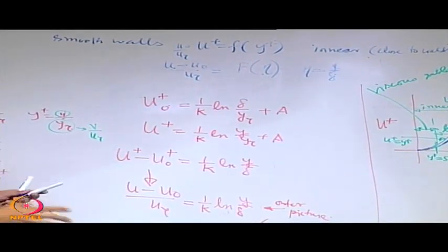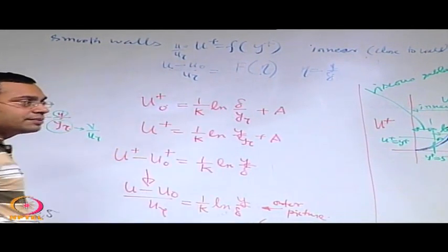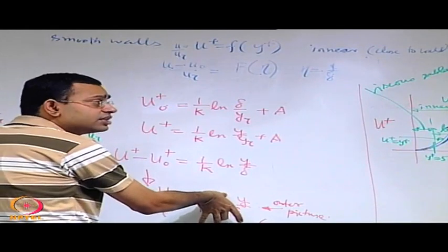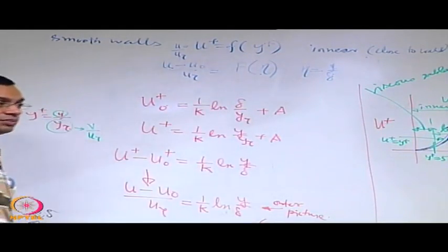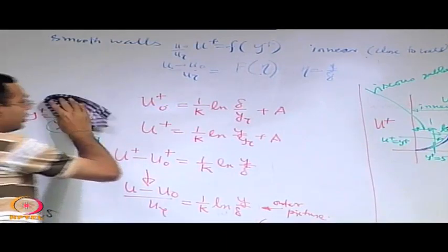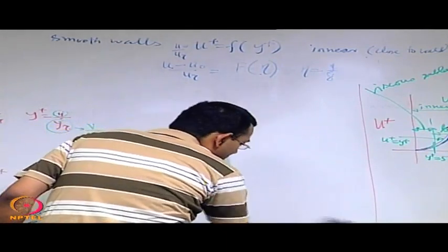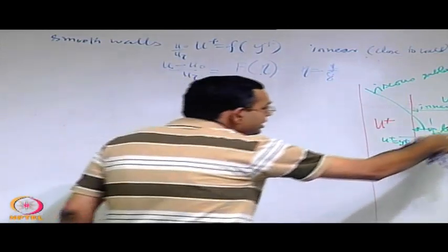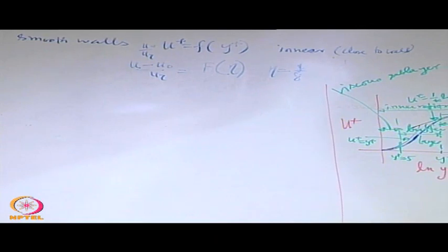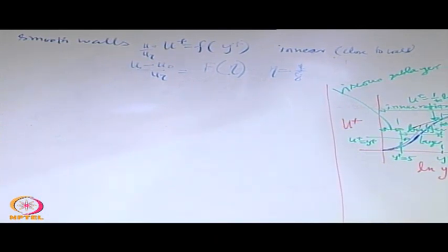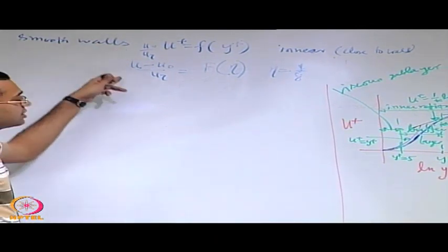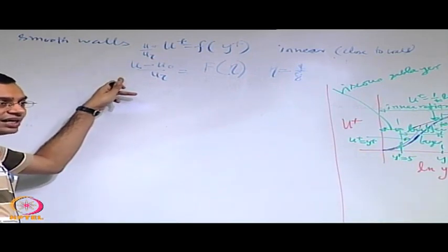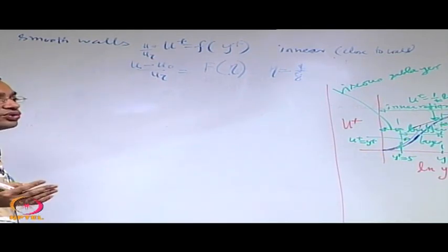This is the understanding that we get from Prandtl's mixing length analysis. These exact functions we may challenge, but the forms we may not challenge, because the forms are the same. Now at the overlap, these functions should behave the same way. Wherever they overlap in terms of their physical behavior, one is taking over the other in a region, and at that overlapping condition you must have these functions giving the same behavior. Not only that, for a smooth transition their derivatives also should give the same behavior.